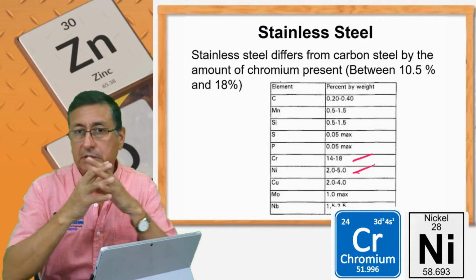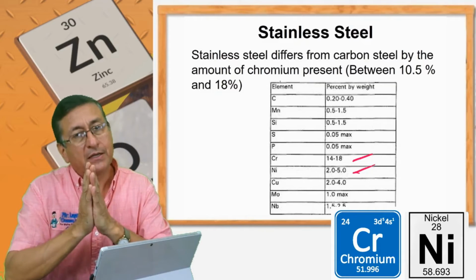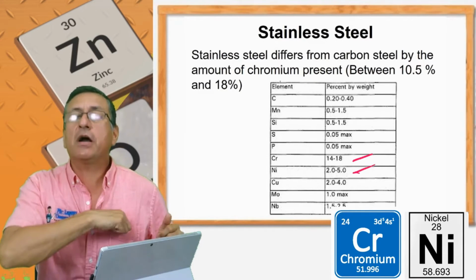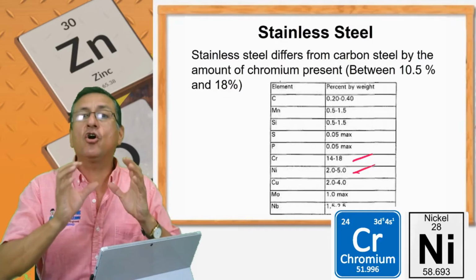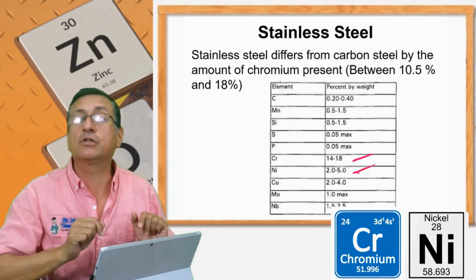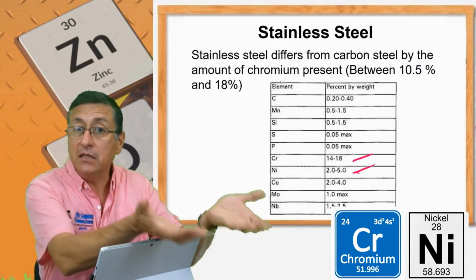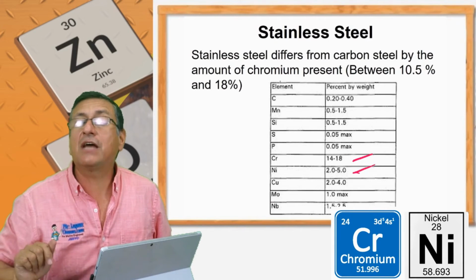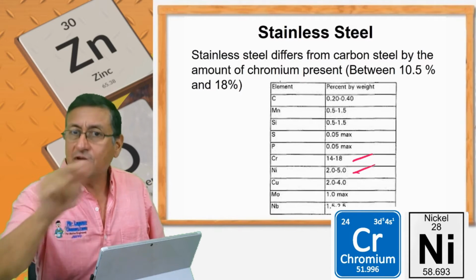Remember, it's important, if you are a marine technician, to keep a magnet in your pocket in order to identify if the bolts and the hardware used by other subcontractors are appropriate in your boat, in your business. The magnet is a good tool, but I have another tip.